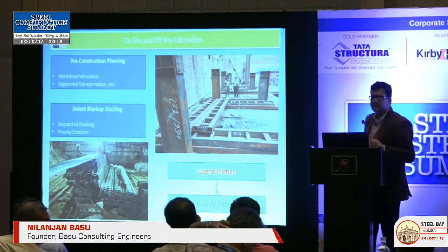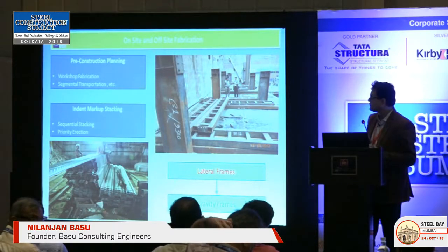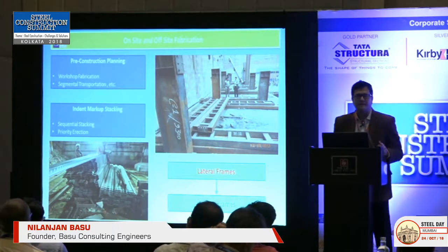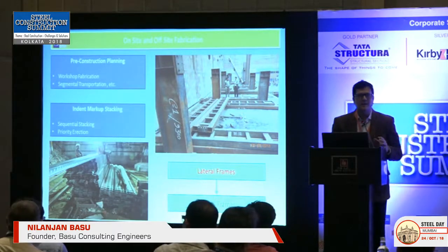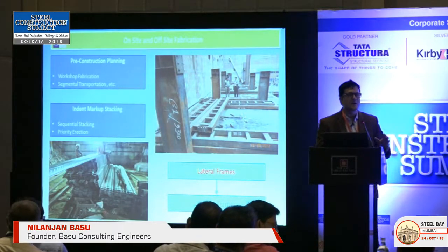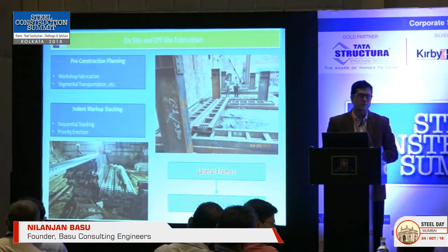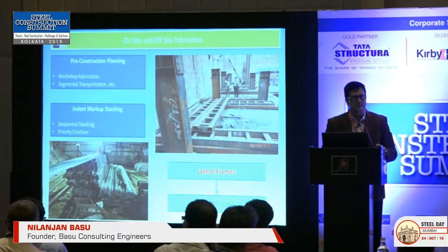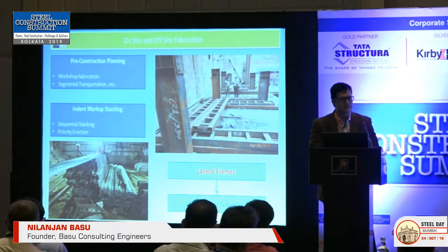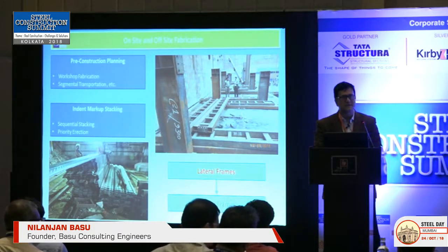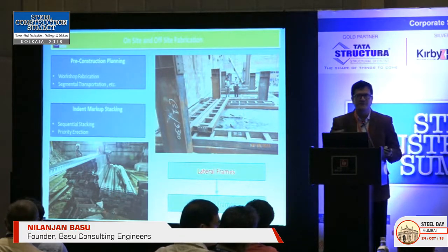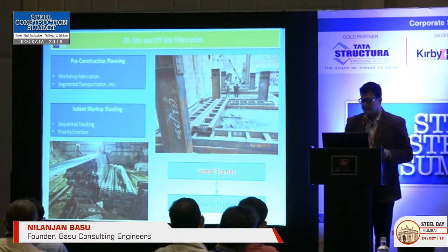So once the material is done, we then call it the indent markup stacking. In the indent markup stacking, we actually tell the contractor which are the materials, where to store, where to stack. And we as a designer or as a consultant get involved in this totally. In the supervision, in the planning of the stacking, in the planning of usage, and the planning of redistributing the material during fabrication and erection.